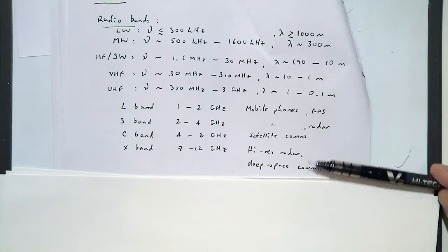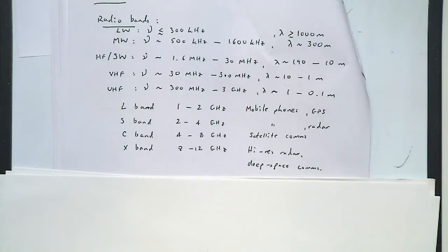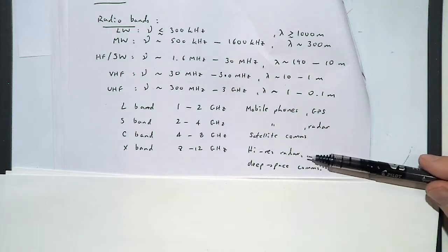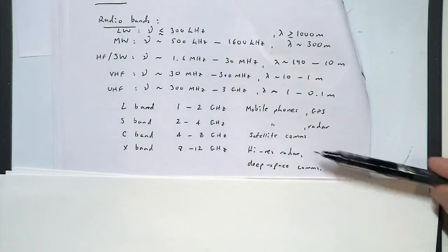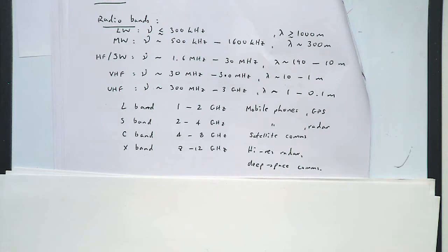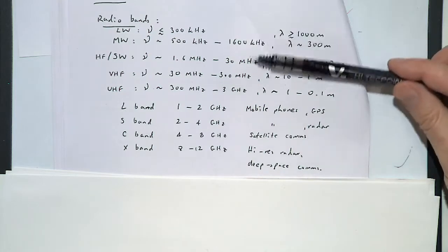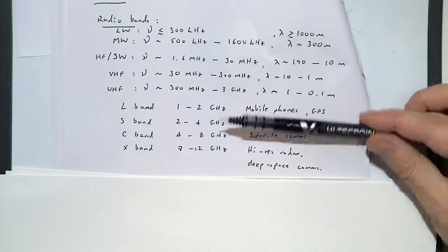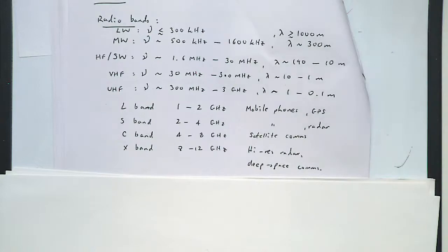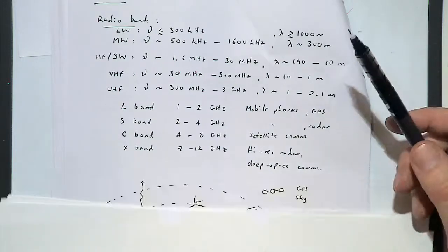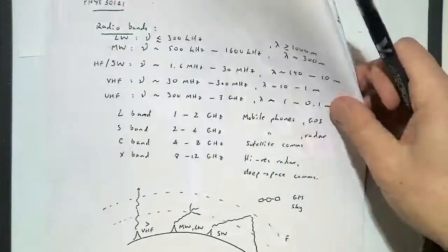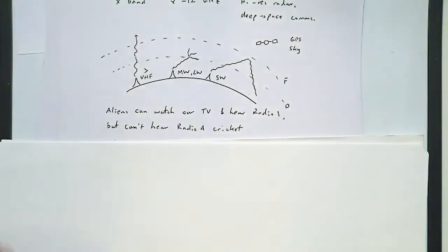And these high-frequency things, they have shorter wavelengths which can be used for working out where stuff is and doing high resolution radar, so you can look at the shapes as well as the fact that you're having a bounce off an aircraft and things like that. And you can also use it for other applications as well. So that's the division. We describe it in terms of wavelength at the longer end, because that's a convenient number, and we describe it in terms of frequency in gigahertz at the upper end, because again, that's convenient. Okay? All right. So what's our summary of that section?